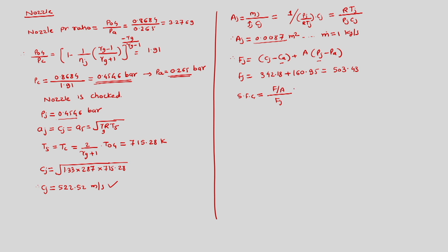Here we are told that this turbojet has a combustion efficiency, so we can say fuel air ratio theoretical divided by burner or combustion efficiency, divided by jet thrust. This will be in seconds, so we will make it into hours by multiplying by 3600.